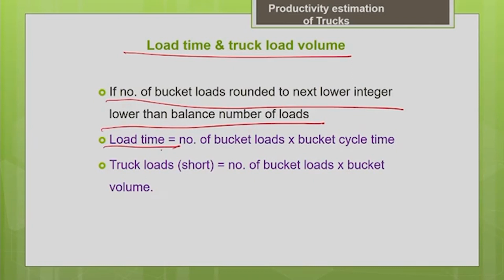Load time is nothing but the number of bucket loads, that is the number of bucket cycles, multiplied by the bucket cycle time. What is the per cycle bucket cycle time? So the number of bucket loads multiplied by the bucket cycle time will give you the loading time for your truck.